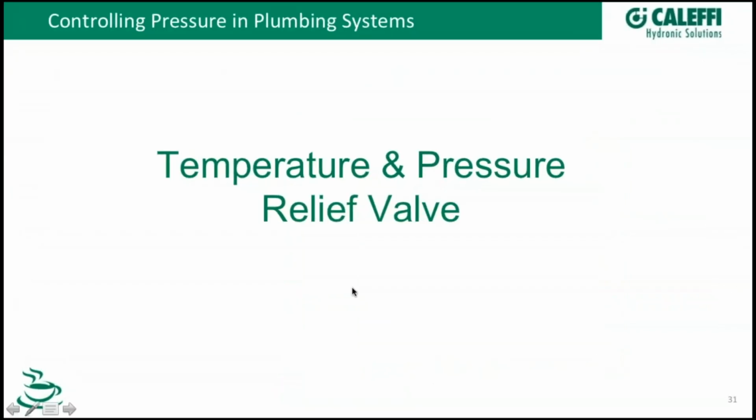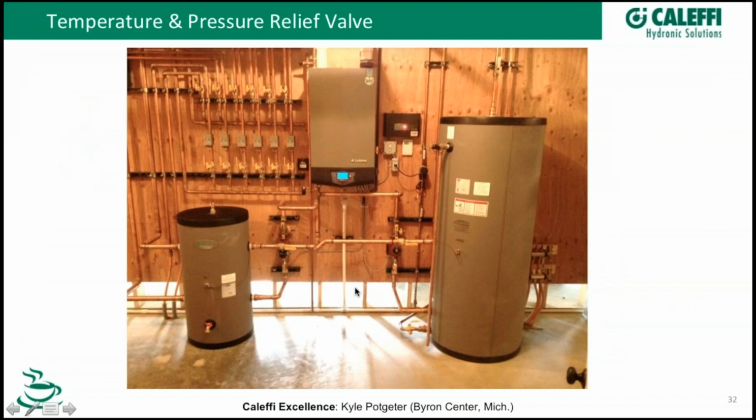All right, a little bit more about the temperature and pressure relief valve. I think I talked about that, but again, it's called a TMP valve because it does two functions, temperature and pressure. These need to be checked from time to time. I've seen them where they lime up, and if you go to pull the lever on them, they won't discharge, it's kind of limed shut.